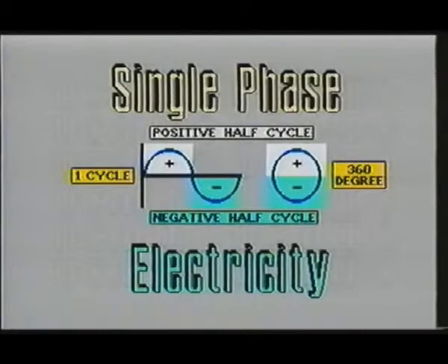As you can see from this simple illustration, the current flows in one direction for one alternation, and then flows in the opposite direction for the second alternation. Also notice that the voltage potential constantly changed values as the sine wave went from 0 to maximum positive peak and back to 0, then from 0 to maximum negative peak and back to 0 again to complete one cycle.